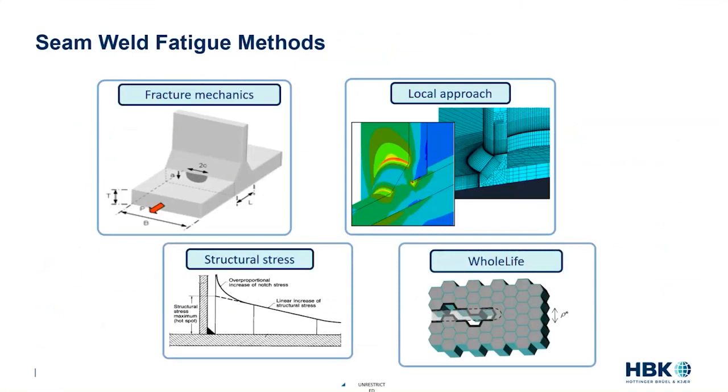With that, you'll see that we have a variety of approaches for trying to go off and life a part due to weld fatigue. And the first one to come up would be fracture mechanics, because basically weld fatigue is a crack growth process. Problem with fracture mechanics, it's very much a point-wise solution. There's a lot of information that has to go in about the start point for the crack in terms of crack size, crack shape, directions, and they tend to drive the entire answer. So one, it's not something that's easily fit into an FE solution, and two, it's relatively laborious. And so we tend not to focus in on crack growth in most cases.